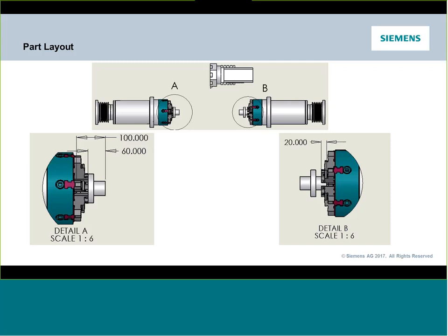Not only do I need to know my part is 100 millimeters, but what is the distance that I want it sitting out of the main chuck when I work on it? It seems silly, but I will hand draw roughly what I want whenever I start one of these jobs. I'll jot down the distance I want to be out from my work holding, and when I go grab it, the distance I want it sticking out once I'm done with the transfer. I like to map that out, maybe draw a quick little picture of the part. This becomes very important when you start to fill out the program, because a lot of stuff we're used to leaving there for graphic purposes becomes critical data when we start running this machine.